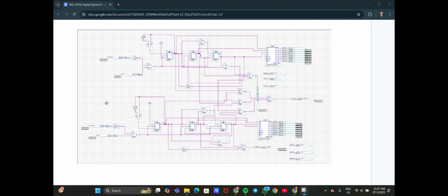standard 6-sided dice. The circuit is driven by a clock signal that synchronizes the state transitions of the flip-flops. The outputs are then fed as ABCD into a 7-segment decoder, which converts the binary values into a format that can be displayed on a 7-segment display. Players roll their dice using button 1 and button 2, which serve as input controls for triggering their respective counters.